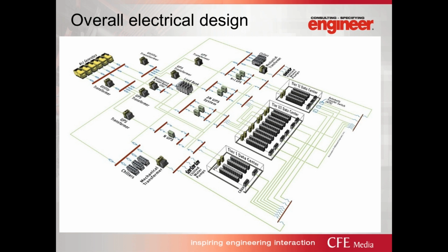Secondly, testing and maintenance. Talk a little bit about the tap cans, which are basically a connection point for either a temporary load bank or possibly a temporary generator or both. If you have a site with 24 generators, it might not make sense to have a tap can for each and have that cost. Or it might not make sense to need to connect temporary cables into generators one at a time to get your testing done.